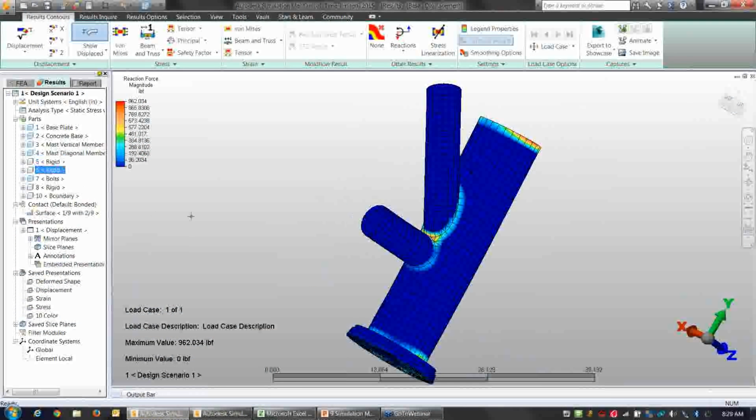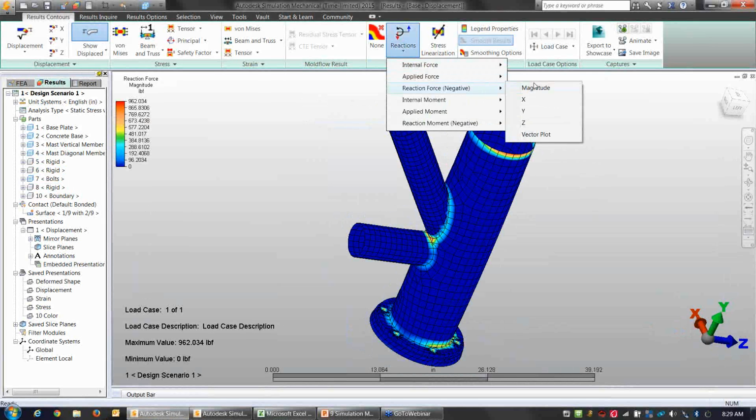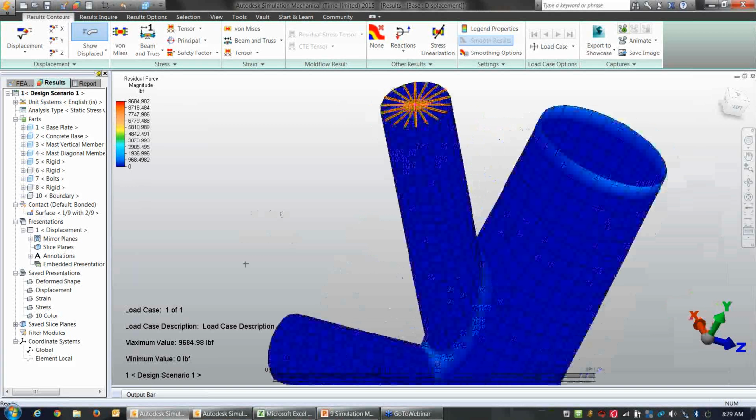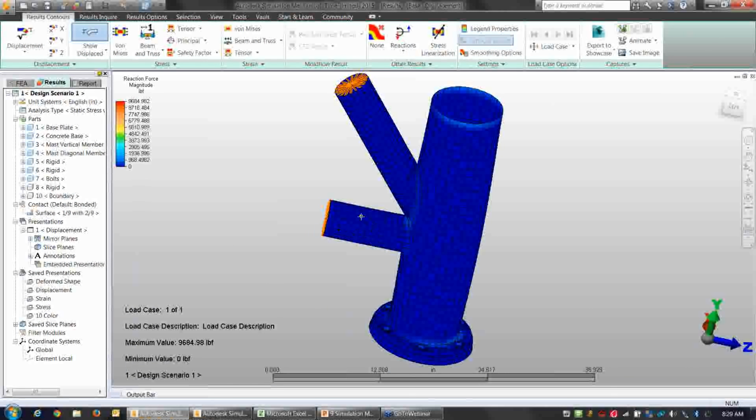That's a good question here. Oh, that's right. I only set this one part to ignore. There's our reaction force on that node. It's because I only set this one part to ignore. That's why we don't see the reaction forces there from the part-to-part reaction forces, because this is another part. But there is our reaction forces for that part and the reaction forces for that part. That's why we only see it on this and along the interface between the two. We're only seeing the reaction forces on this part, because these are set not to show.